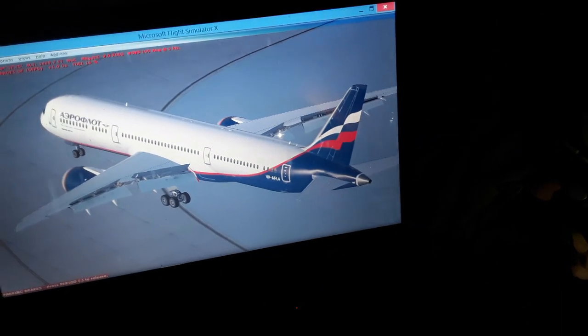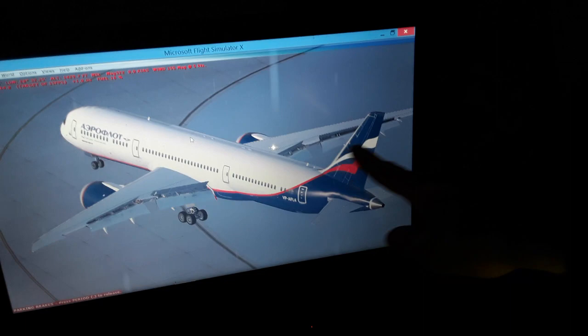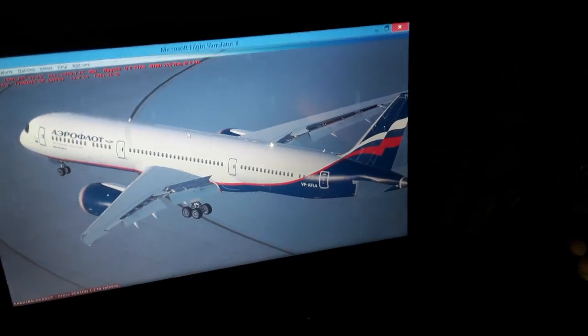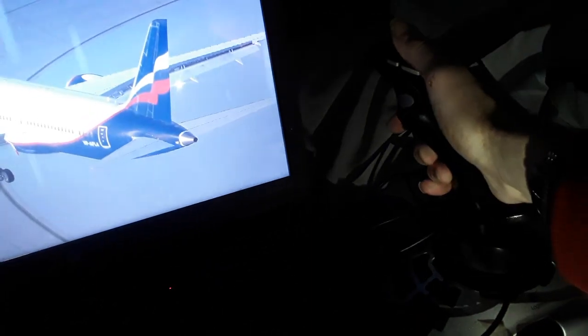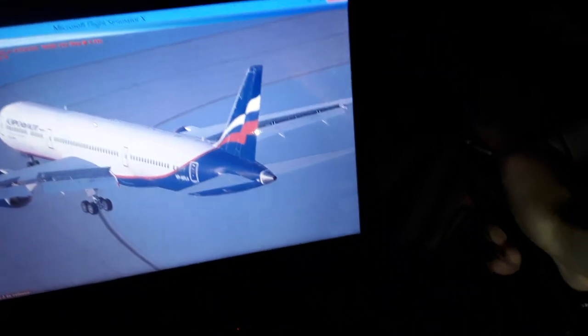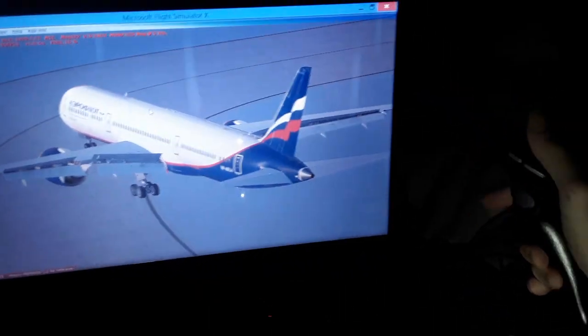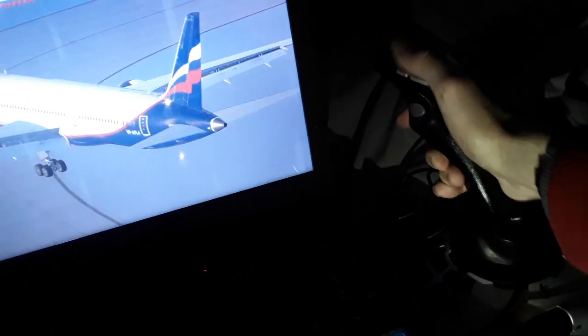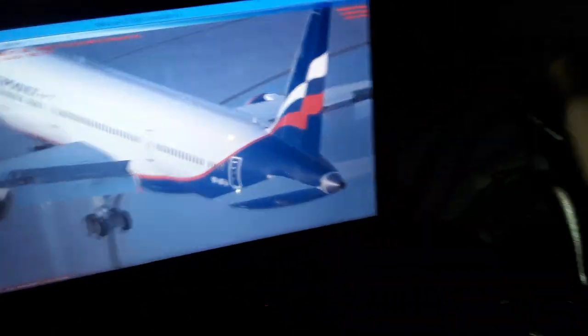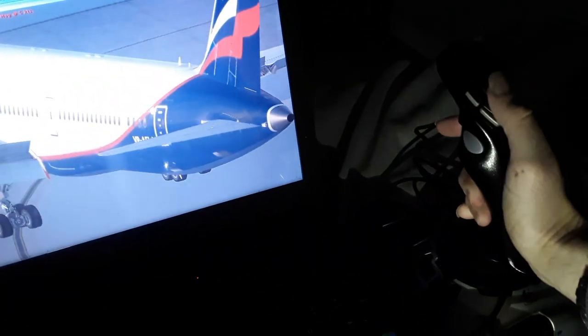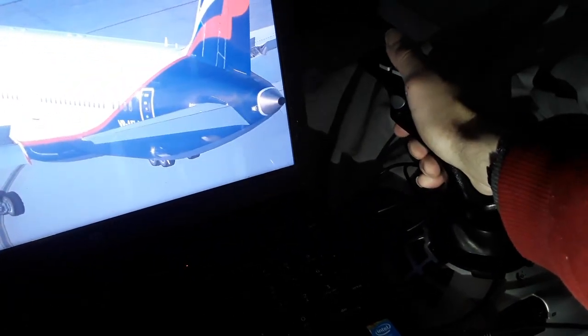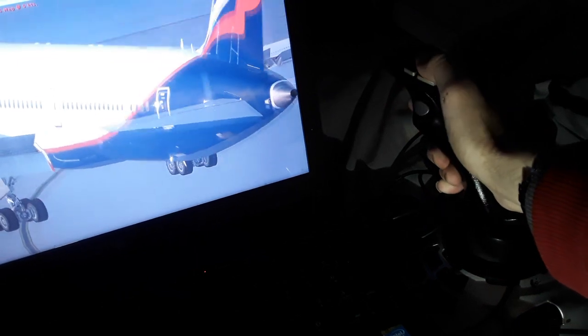We have also the lateral axis from wingtip to wingtip over here, which is the pitch axis. The pitch axis is the elevator like this. You can climb and you can descend the aircraft using the pitch axis over here, the elevator for climb and for descent. As you can see, the horizontal tail of the aircraft.